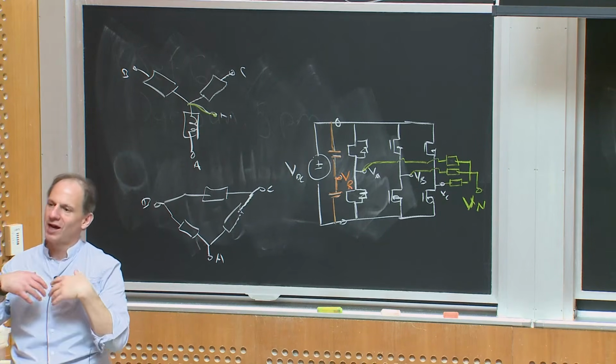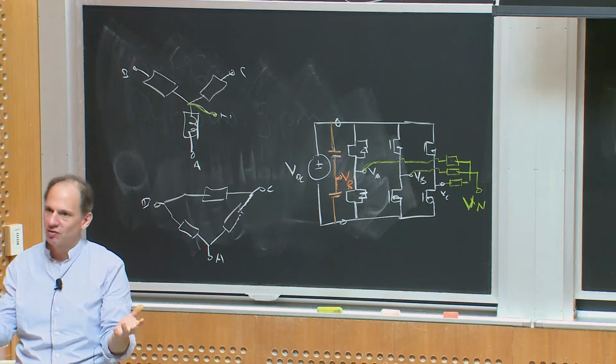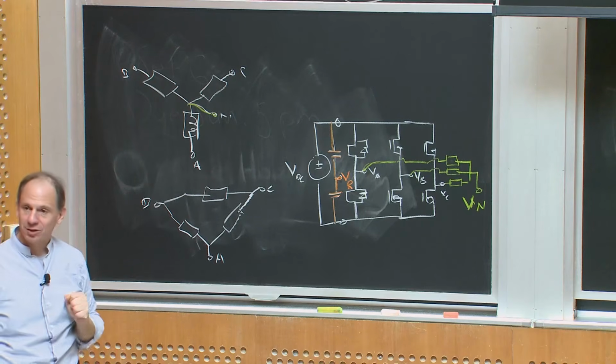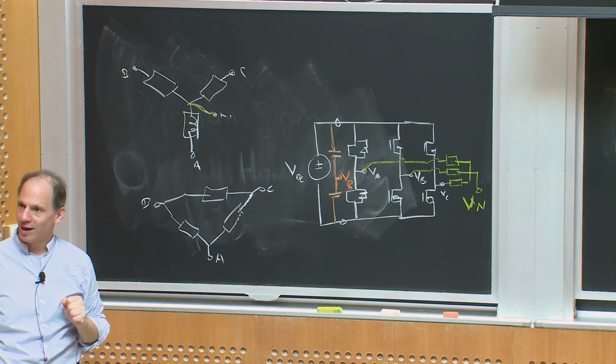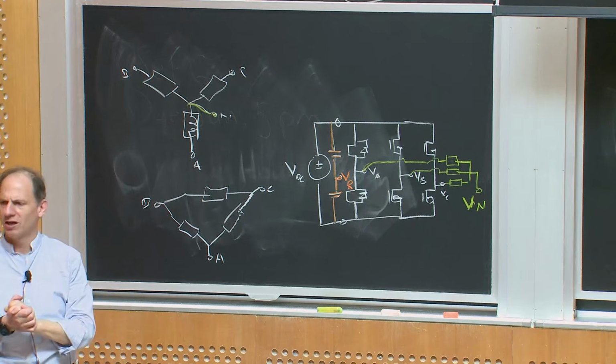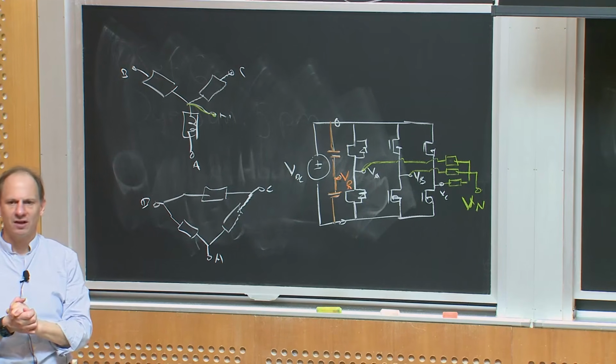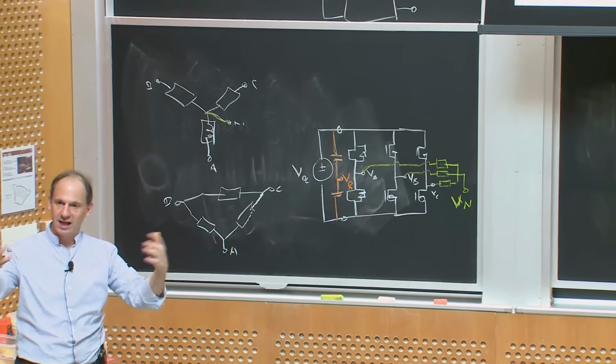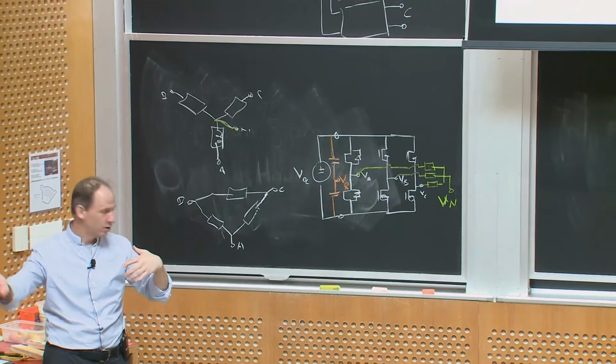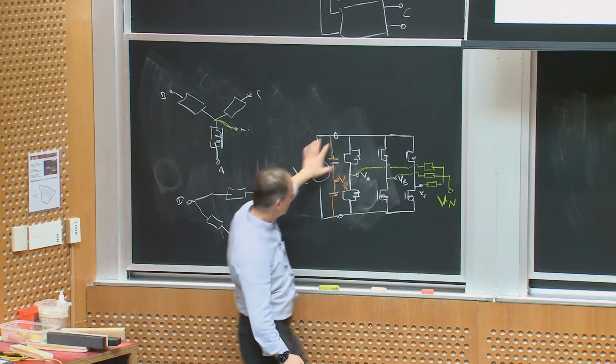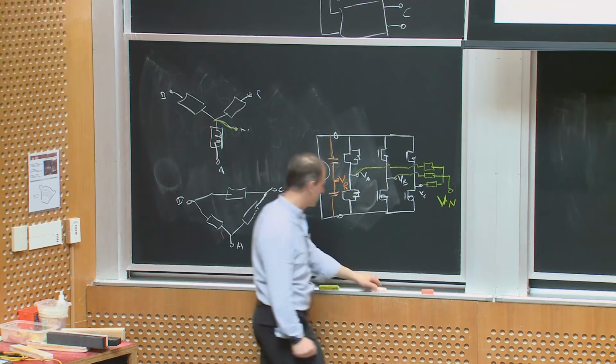So in very specialized high speed machines, for example, you might go for the top solution of independent phase drive if you're allowed. But the vast majority of 3-phase inverters, or 3-phase DC to AC converters, where power could flow either direction and you have active control, use this 3-phase bridge structure.